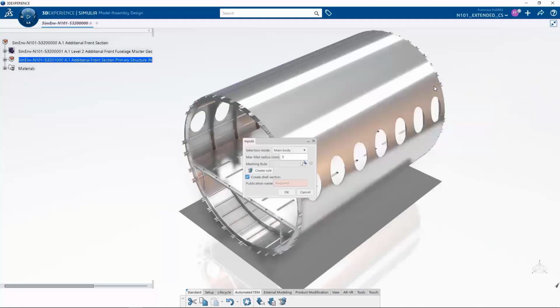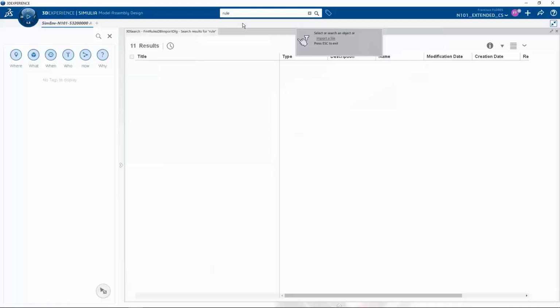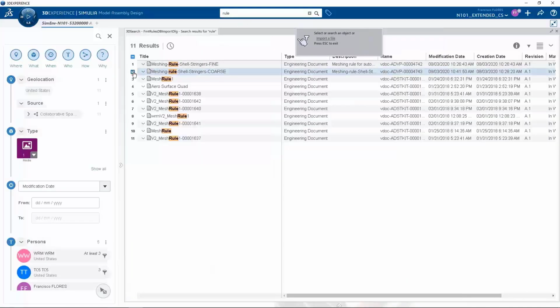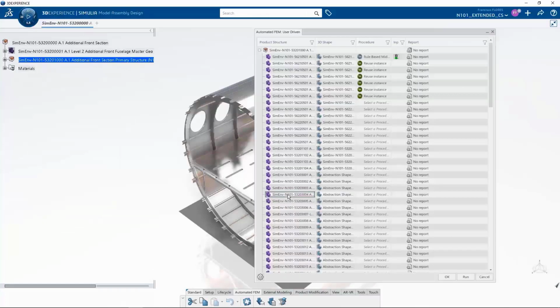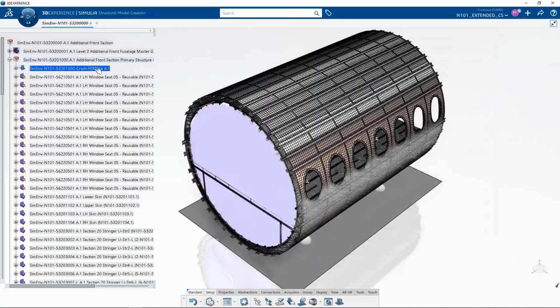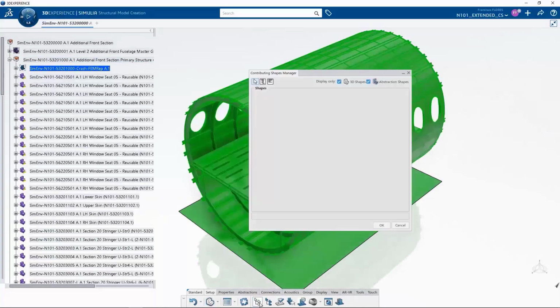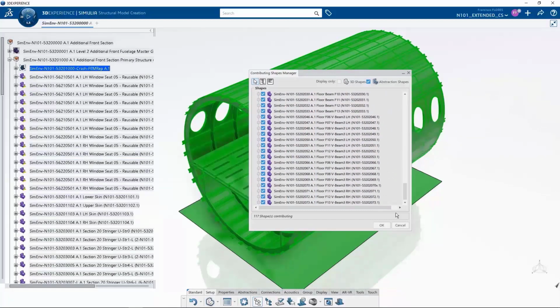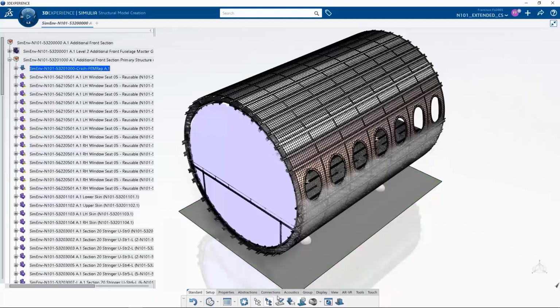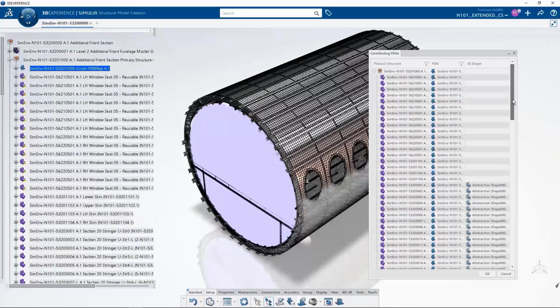Much like before, we will go for a rule-based meshing procedure, which can be seen as a semi-automated meshing procedure. After having defined the part that we want to mesh, and after having defined the meshing rule, we can just run the automated meshing scripts from the platform and create, well, as easily as possible, some meshes for the relevant parts.